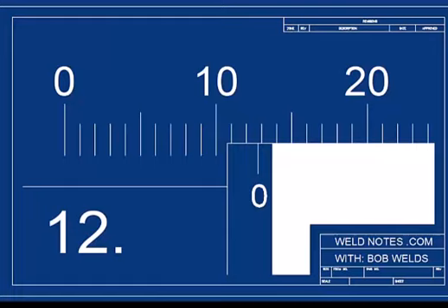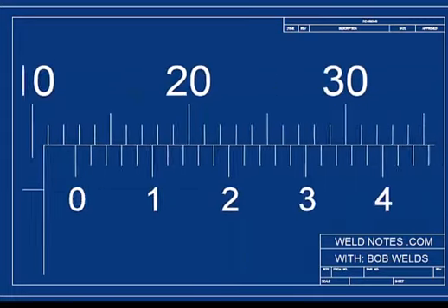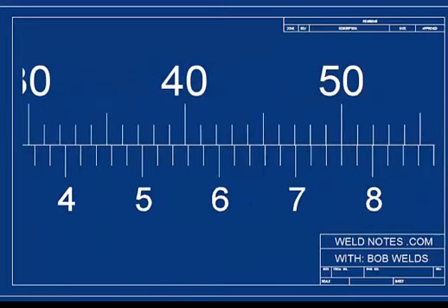But first, remember the trick? See how the reading is beyond halfway between the marks? That means we need to look on the high side of the vernier scale. I'll slide the view down there and let you look. Now here we go. Pause the video and look carefully. The mark that lines up best is here. Now, what number is that? This is the 0.7 mark. So 0.72, 0.74, 0.76. The answer is 12.76.